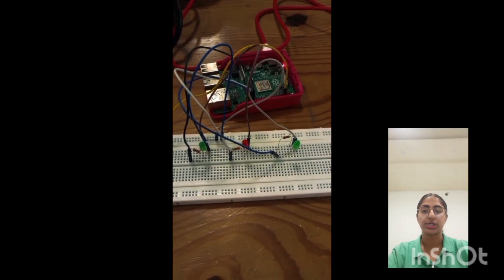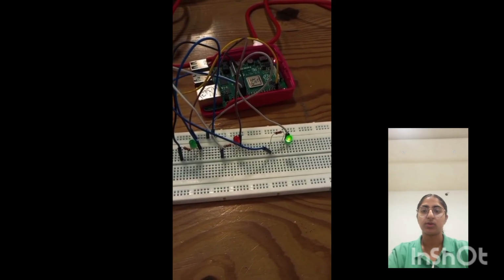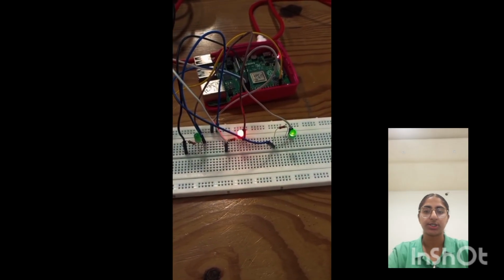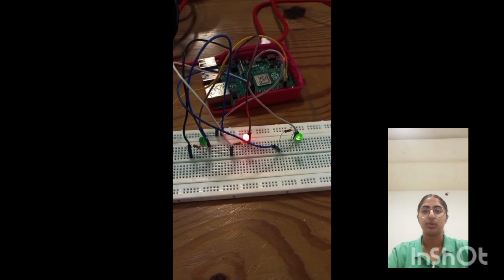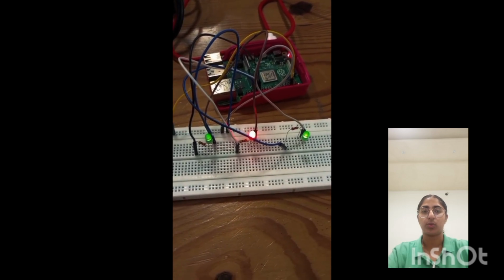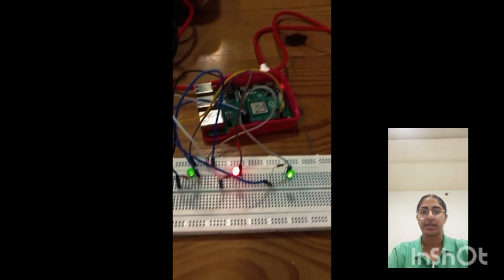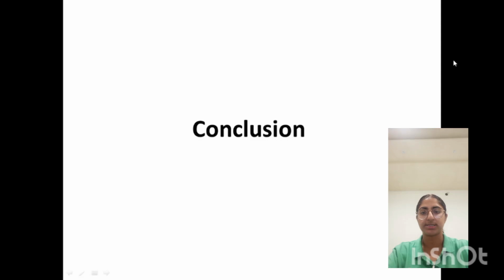If I talk about the challenges I faced while working on this task, one of the main challenges was syncing the tkinter GUI updates with PWM signal changes without delay. Initially, the brightness slider updates lagged slightly, but by refining the callback functions and optimizing the PWM signals, I achieved smooth real-time response. This task helped me understand how embedded systems combine software interaction, signal generation, and hardware control.